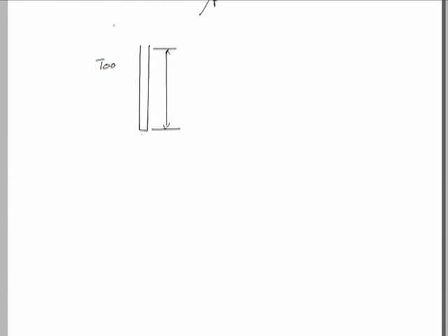As we have seen in micro features, if the tool is like this, in which the length is much more, the slenderness ratio is much high. So, here the strength of the tool is to be considered. It can buckle under the load, and the wearing of this tool will be much faster than in case of a bulk tool.